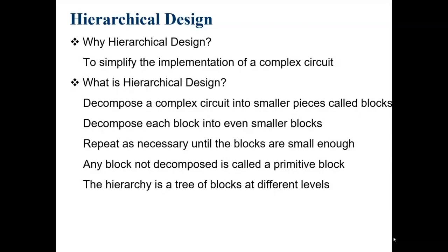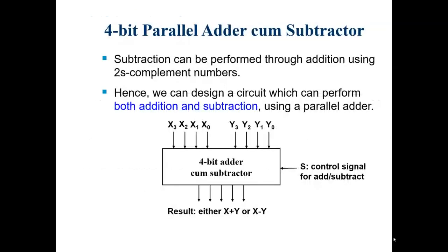In the hierarchical design approach, we decompose a complex circuit into smaller pieces called blocks, then decompose each block into smaller sub-blocks, and repeat until the blocks are small enough. It is based on the algorithmic principle: if we have a complex circuit, we divide it into many small circuits and then connect them together to build the whole thing. Let's say we want to design a 16-bit adder. We connect the 16 1-bit full adders in some particular fashion to design the big block.